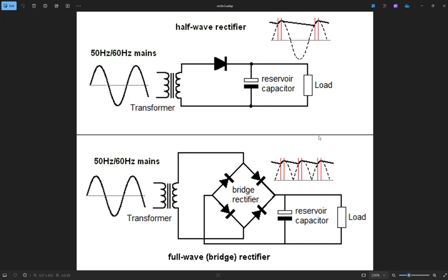So eventually what's happening is, for the full-wave rectifier, since we haven't learned diodes yet, it's just a one-directional current conduction. But if you have a full-bridge rectifier, it's able to flip that negative swing to the top and eventually use the low-pass filter to get rid of these oscillations. So it's converting AC signal to DC.